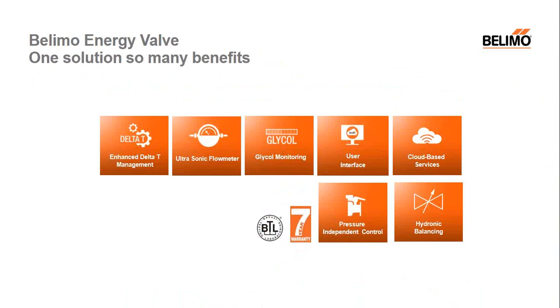So what we've really been talking about here is one solution with so many benefits. We talked about the Delta T Manager and how it's going to optimize overall coil efficiency. We've talked about the ultrasonic flow meter and the advanced technology there, and the ability to extrapolate glycol percentage, the web interface allowing you to connect to valves located all over the building. We've talked about the cloud-based services. At its core, it is a pressure independent control valve, so it eliminates the need for hydronic balancing valves and circuit setters. So it's really one solution with multiple benefits.